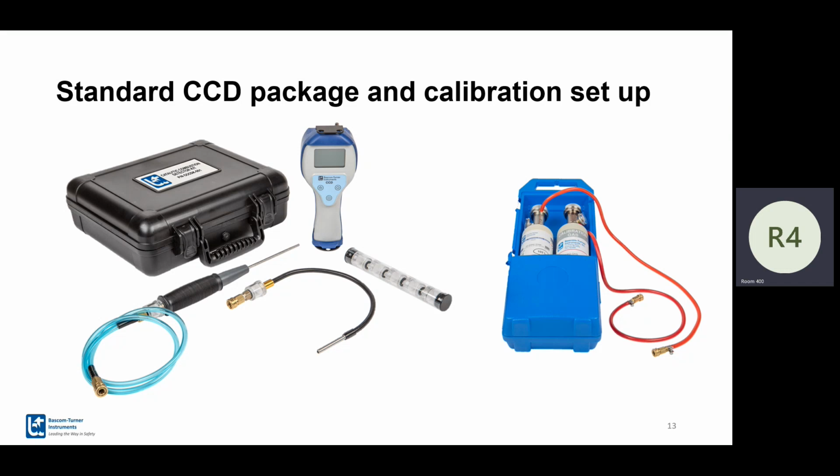So you can put two filters on? You can, they all screw and stack on top of each other. So this is our standard dust and water filter. If you're in a desert environment, it might behoove you to put an additional HEPA filter on top of it. That is something, for example, Southwest Gas uses as standard. They do a double filter stack because they're in the desert. Fine particulate does get in and pump heads do not like fine particulate.